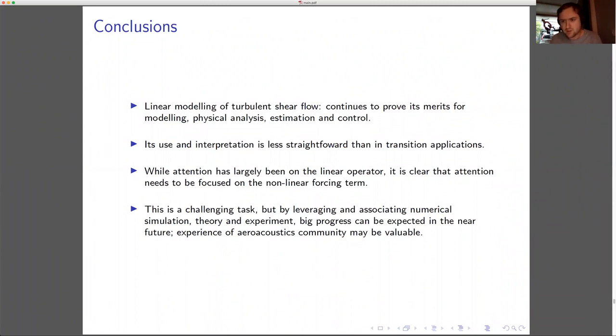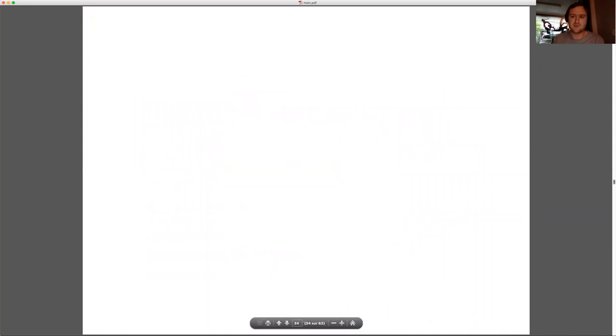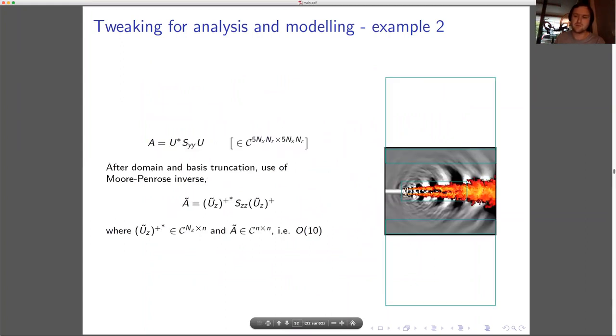In the meantime, I have a quick question, actually. Peter, when you were showing the plots with your collaboration with Ethan, Aaron, Tim, reconstructing the jets' cross-spectral densities, I was wondering about the eddy viscosity that you used. Was that just used across all Strouhal numbers and azimuthal wave numbers, or was it specifically optimized for the parameters that you were looking at? Because I know that Ethan's been optimizing it across azimuthal wave numbers and different Strouhal numbers. So I was wondering, is that eddy viscosity uniform across all of those parameters, or is it a function of those parameters?